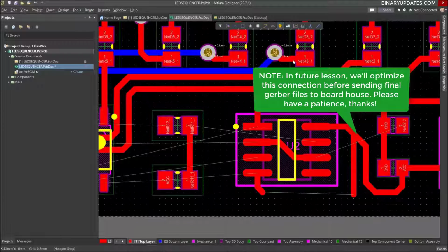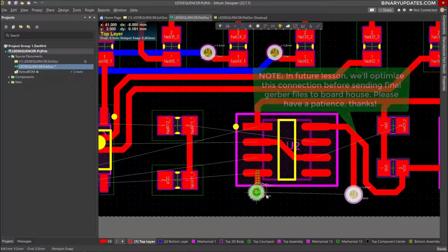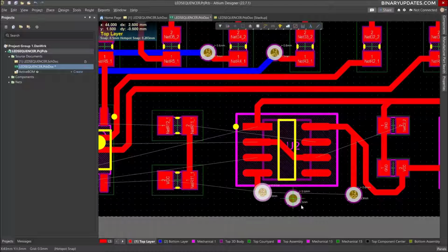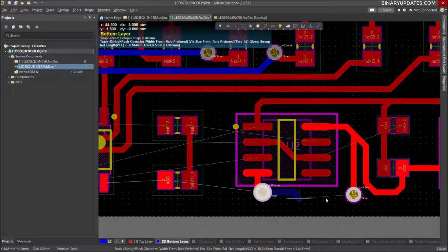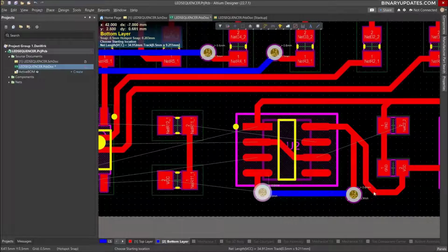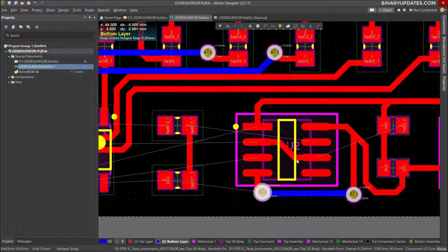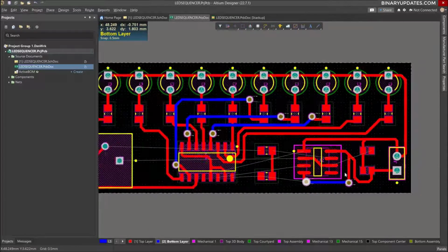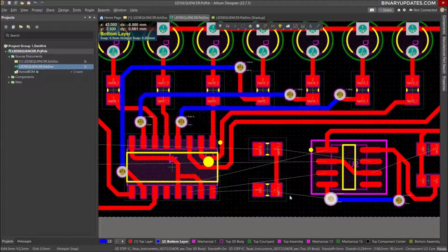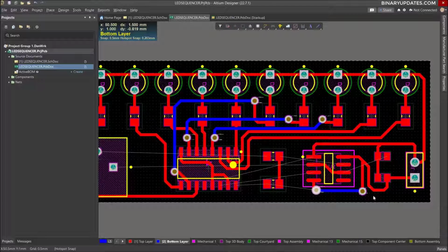Okay, just to finish this quickly, I would just put some vias here and then select the bottom layer, and I want to connect. So press escape, and I think Control S to save the changes. Now what else? I would of course later work and optimize this. I have to figure out how I would finish them.